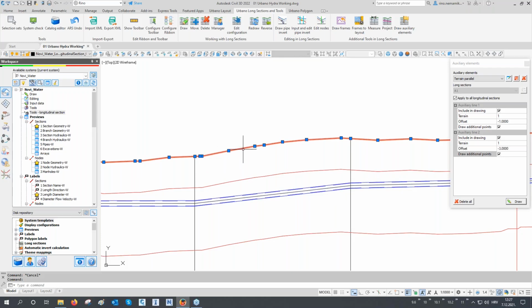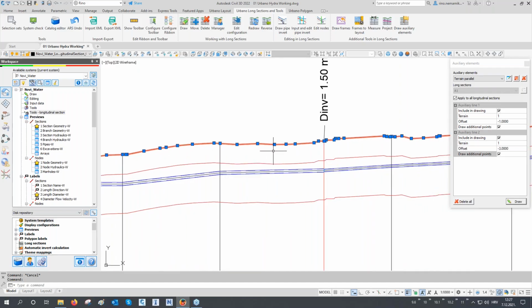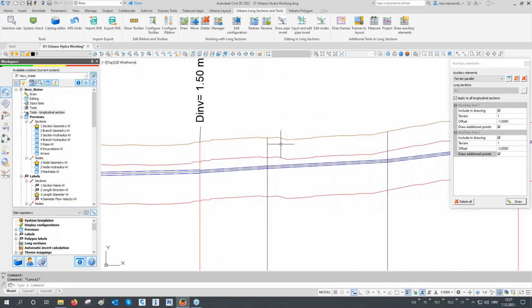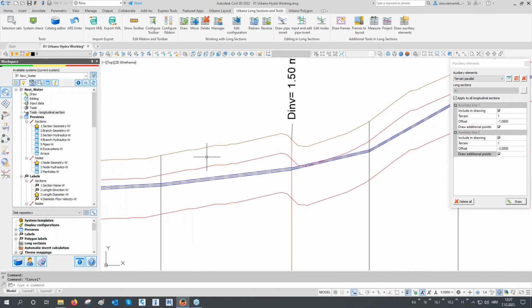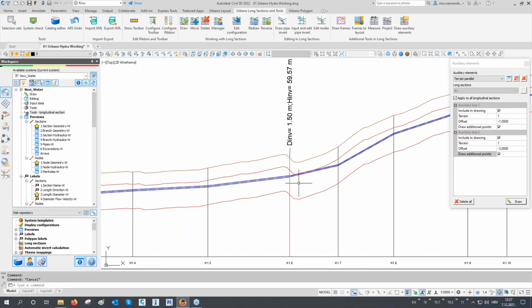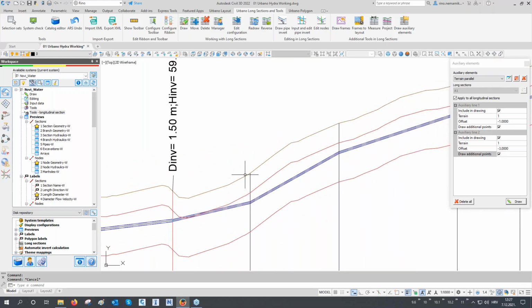Of course, if you notice that some points are not surveyed correctly, you can also delete some of those additional points. But it's really important to have them because later on we will also calculate the trenches and the excavation volumes. So it's not the same if this line here is straight or if it goes up and down, because with the volume calculation that we will run later, you would basically not get the right excavation volumes.